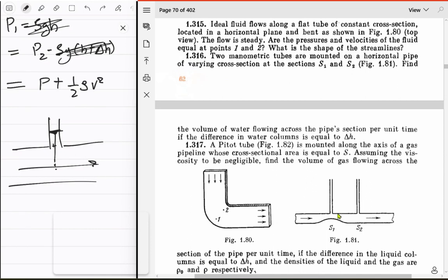Because if there are viscous forces, what that would mean is that this surface cannot have u equal to 0, unless this whole thing has u equal to 0. Actually what's happening is that it's kind of a gradient. So this is our velocity profile: there's 0 at the wall, and in the middle you have high velocities. In this region viscous forces are 0 because the velocity is not changing all that much. In this region though there is a lot of viscosity, and at this point you have 0.